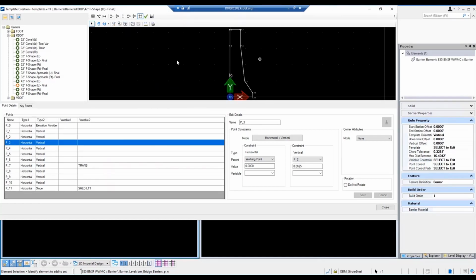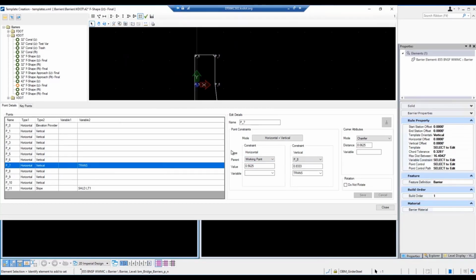The other nice thing about the 42 inch bridge rail, you can see the 10 inch section that's applied here, and that is, so it's the 32 inch bridge rail, so 0.8 is still defined off of where 0.11 ends up, 32 inches up, and then 0.7 is actually a variable constraint so that you can define this bridge rail as being 32 inches tall, transition up to a 42-inch tall deck or bridge rail to a certain station, transition back down to a 32-inch bridge rail.